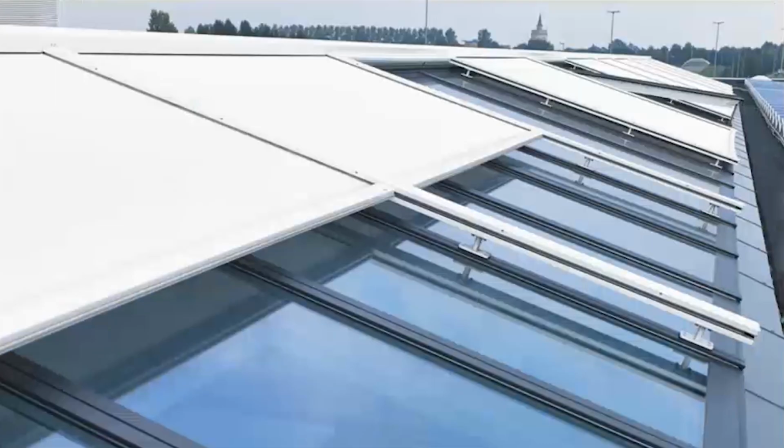What is optimal on the blind side of things is when you do exterior blinds. And this isn't a popular approach in North America. It is much more popular in Europe, and I think it's extremely clever because this approach could allow you to use high solar heat gain glass, so that in the heating season, which is most of the year in Canada, you can benefit from the heat coming in through the glass. And then at the peak parts of the day in the summer where you don't want the solar heat gain, you could close these light transmitting semi-transparent blinds to cut down that heat gain. So it's a super clever way to approach solar heat gain and optimize energy over the year.